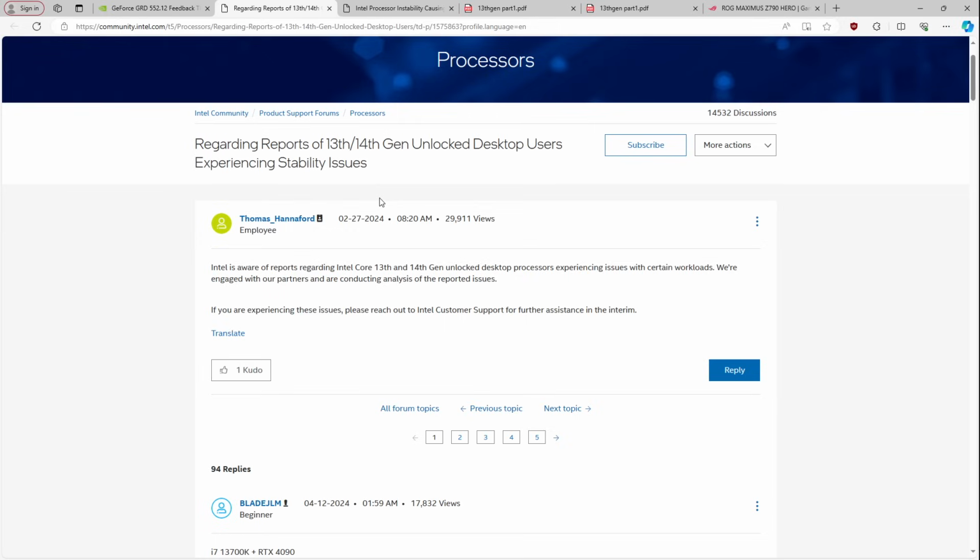You can't have any safety margin on that. That has to be within like 10 millivolts of what won't run. And so once you have that data, of this frequency at this absolute minimum voltage, then 3 months or 6 months later, you can go back and test that frequency at that absolute minimum voltage at the same temperature, right? Because if the temperature changes, that will actually change the voltage requirements slightly. And if you find out that these settings that worked 6 months ago don't work anymore, they require 20 millivolts more or 30 millivolts more to work, then it's like, okay, that CPU is degraded.